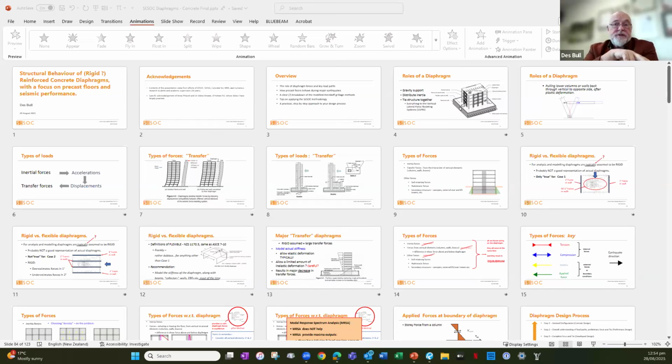You end up finding yourself in two situations. If you've actually got a step in the diaphragm, like forming a Z, you would track the loads through that horizontal, vertical sub-wall and back into the next diaphragm. Basically, it's behaving like two beam column joints above one another. So there's a strut and tie solution to that. People have done it and made it work or come up with a rating for that.